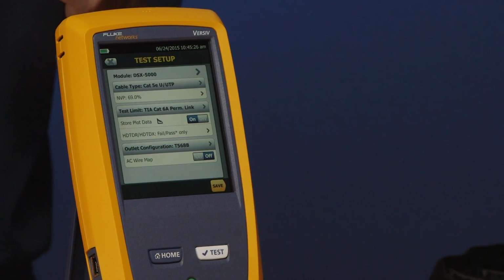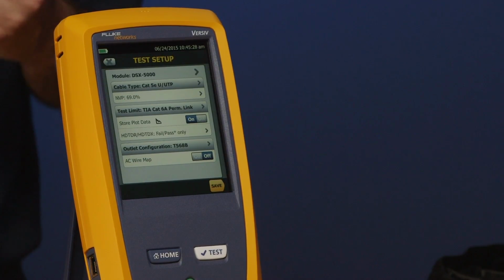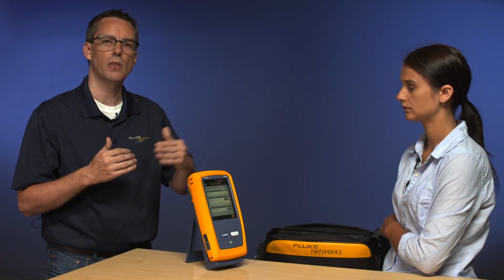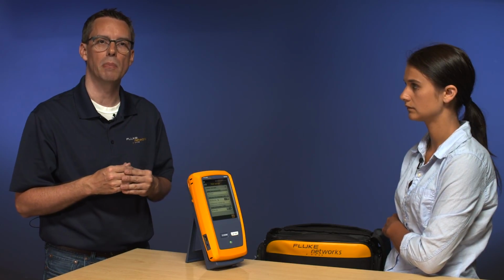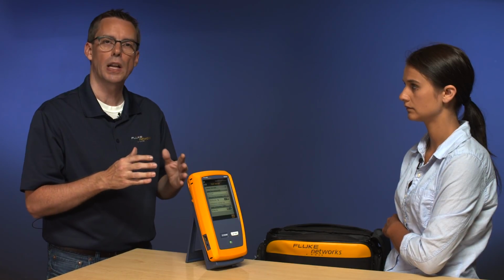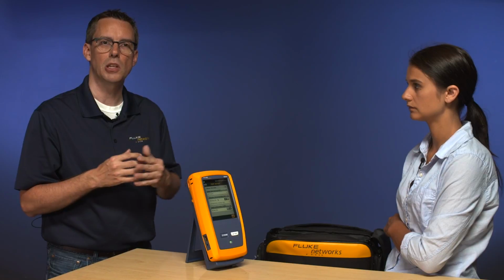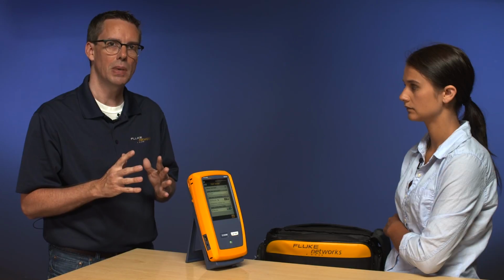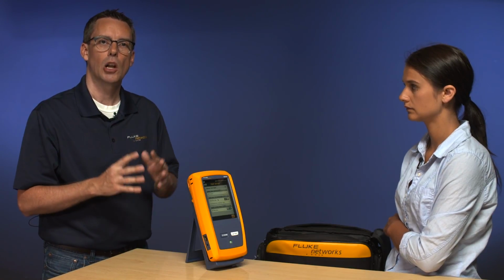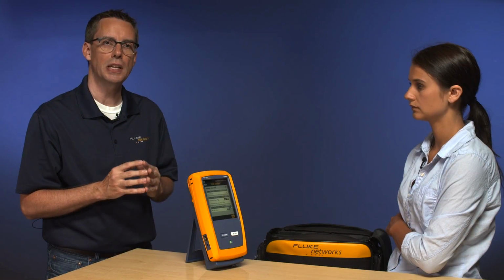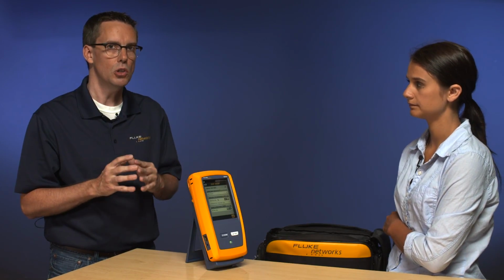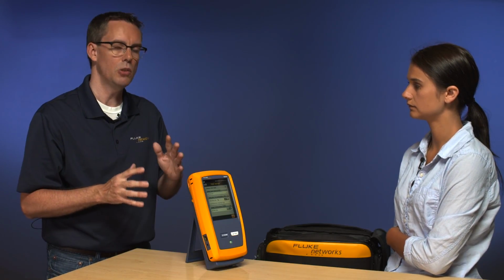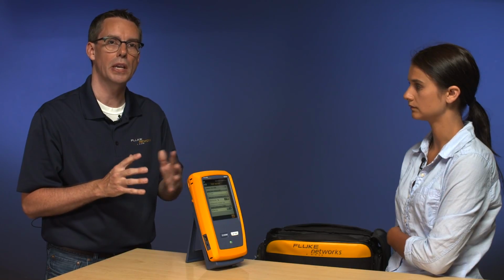Okay. Just below the cable type selection, you're going to see MVP. That's the nominal velocity of propagation. What that is, it's a value that determines what the length of the cable is. It affects how the length of the cable is being measured. So if you set this value incorrectly, then your length measurement is going to be incorrect. Nothing else will be incorrect, it'll be just your length measurement. Best way to do this, I recommend, go to the cabling vendor's website, look at their data sheet, get the MVP off the data sheet and put that in the tester. You could use the library, but cabling manufacturers are constantly improving and tweaking their cables, and we may be a software update behind on what they're currently making.